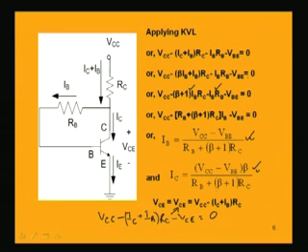So, now we are having the operating point defined by IC and VCE. Having known the operating point, now let us see whether the bias stabilization is satisfied here or not, meaning the change of beta will affect the collector current in what way.